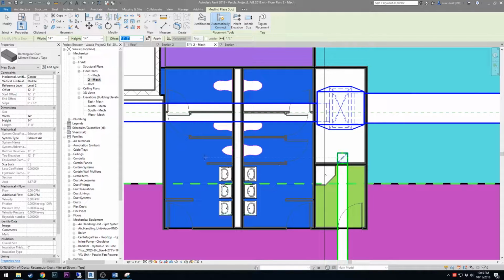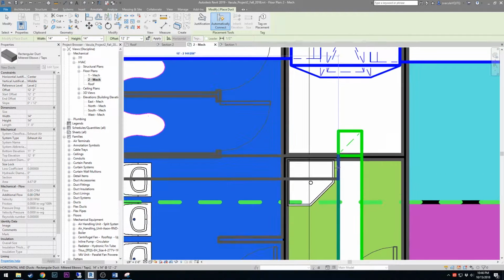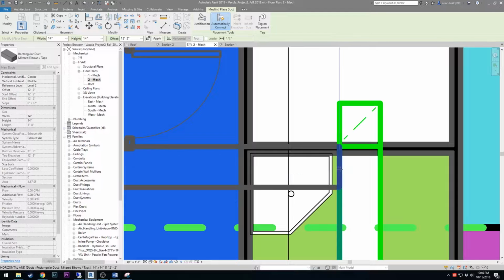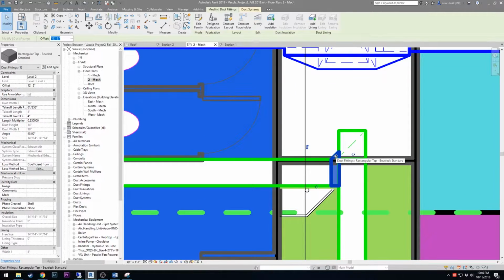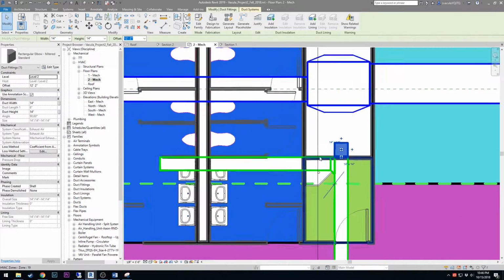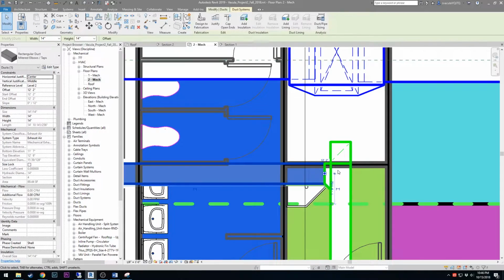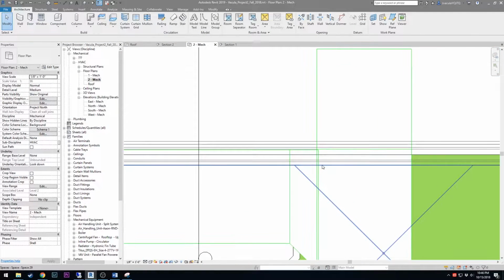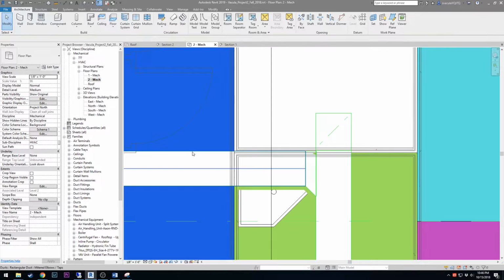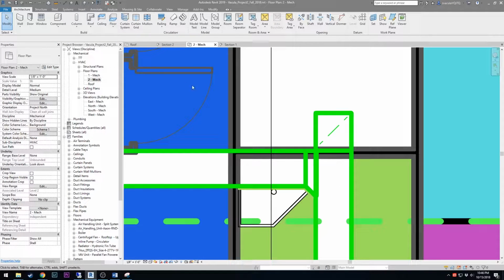I'm going to pull this over here. I'm going to pull it, and you want to make sure you hit your ductwork, not the elbow transition here. You want to keep these taps off of the elbows. So if you do accidentally hit it and it's into the elbow, let's turn on thin line to see. Yeah, it is a little bit. And just click and move him down a little bit.